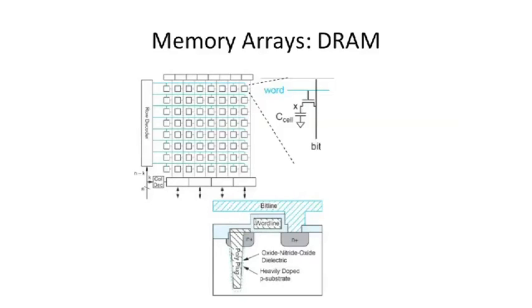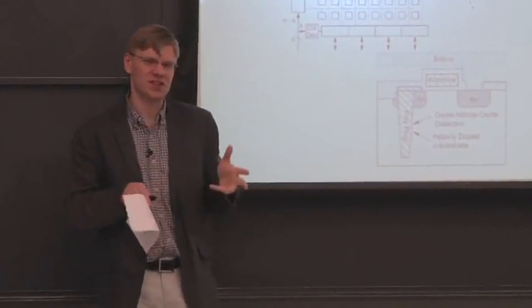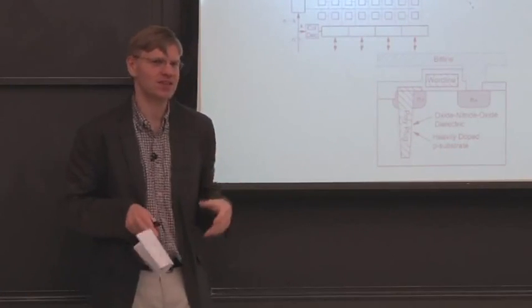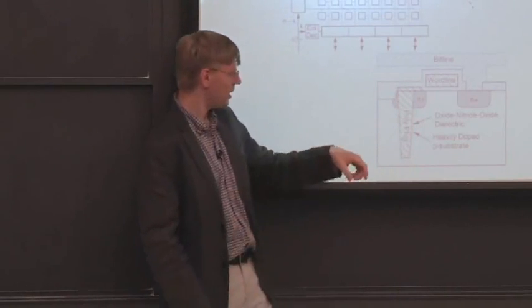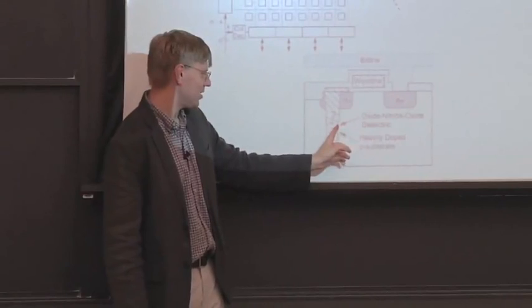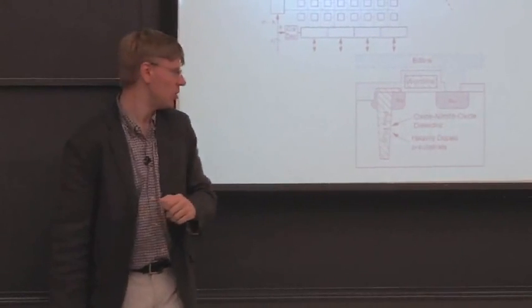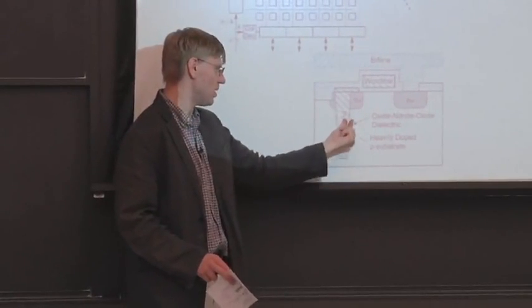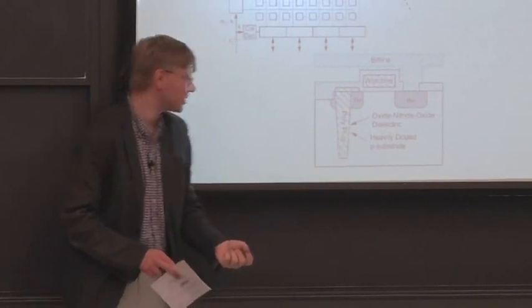It is a capacitor, but it's a very oddly shaped capacitor. Typically, what will happen is you build these very, very deep trenches, very long and skinny trenches. They're skinny because you want to put them very close together, because if you want gigabytes and gigabytes of RAM, the smaller you make it, the more you can shove on a single piece of silicon. But you have these really long and narrow trenches here, and you have 2 plates of metal and then a dielectric in the middle. So in this case here, I think there's 2 metal plates here, and then there's some dielectric shoved in between there, but you can't really see it on this picture.